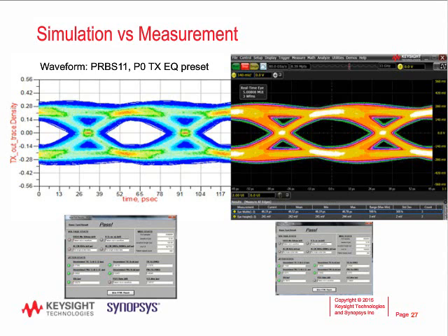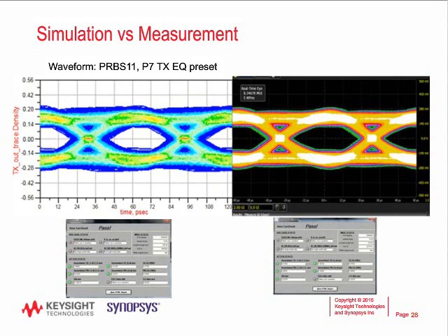We repeated the same procedure for preset 7, still using PRBS 11. Again, as can be seen, there is very close correlation between simulation and measurement results, and both of our waveforms are still passing the SIG test.